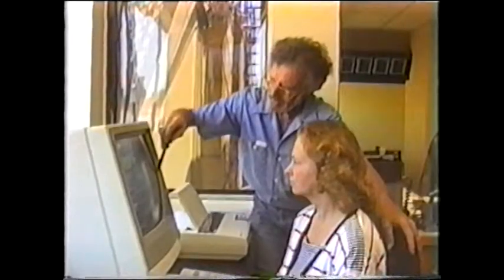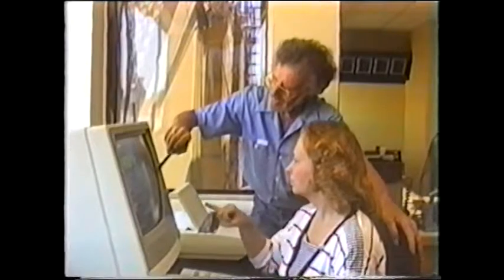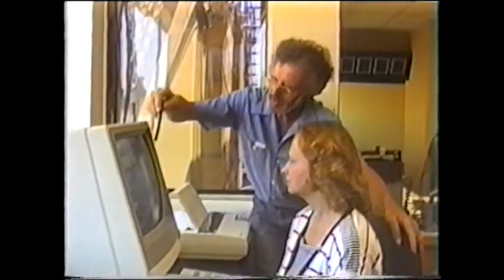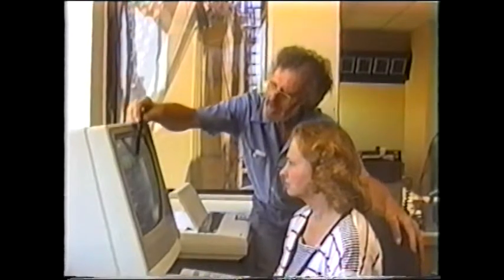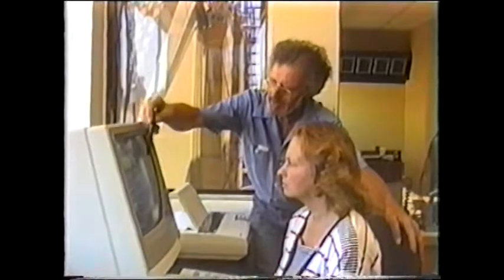The simulator mode is an important part of the diagnostics process. Each Impulse system can simulate plant operation without actually firing any motors or running mix. This is a very useful tool in diagnosing problems as well as training new operators. What do I do if the belt doesn't start? Well, what you'll have to do is you'll look at the screen, and right here, you notice it says the drum bypass. Okay, you have to turn this off.